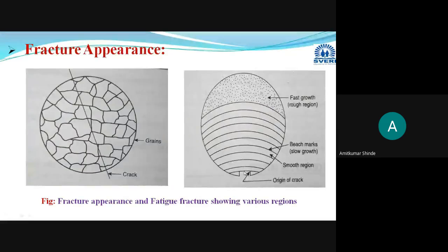The spacing depends on the vibration, or on whichever amount of stress is there; depending on that, the distance between these beach marks will change.